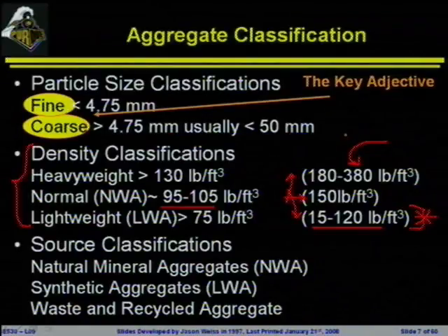Nuclear. All right, the nuclear industry is very excited about heavyweight concrete because it can help in shielding. So typically they will replace the normal aggregate with a much heavier aggregate, like maybe a steel aggregate or something like that, that'll go into the system to really increase the density of the system with the idea of shielding. There'll also be quite a bit of recycled aggregates coming out, synthetic lightweight aggregates, other things that we'll talk about as we move